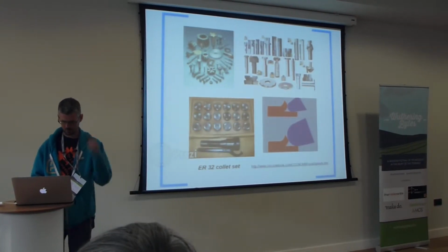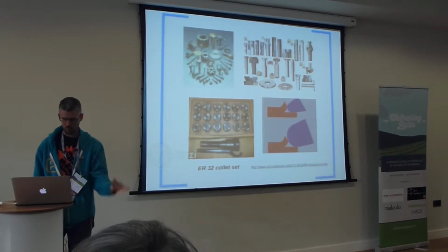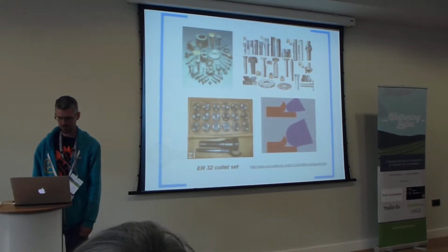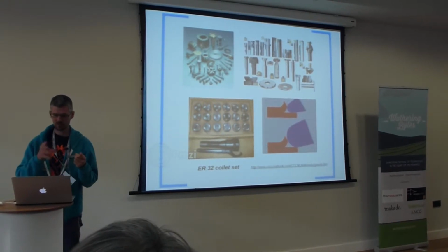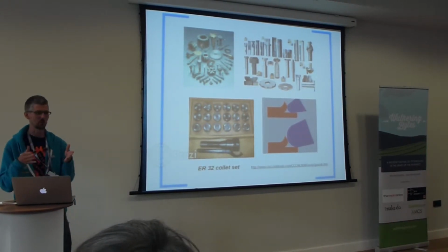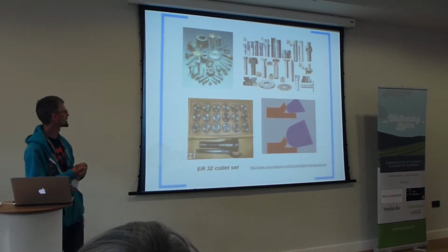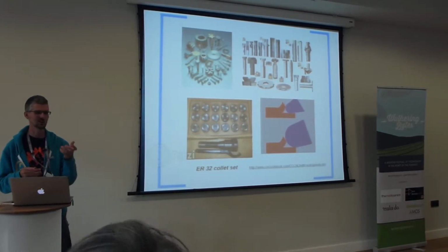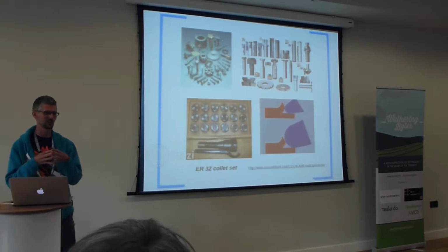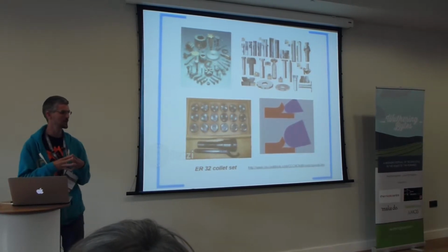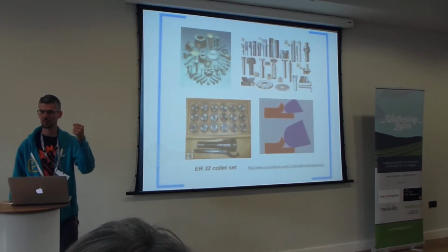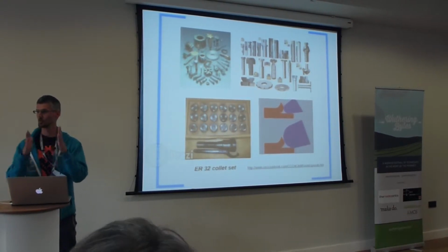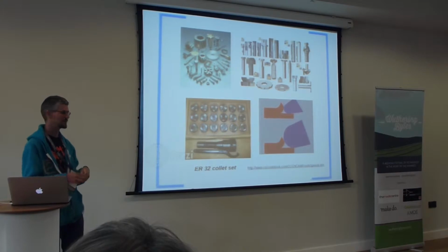So on to tooling. If you're used to things like pillar drills or cordless drills or whatever, you're used to having a chuck that can take any size bit, but the way that milling works is you usually have a specified shank size and then you get a range of tools with that shank size. So if you're, say, doing PCB work, pretty much the standard is 1/8 of an inch, so you need something that's going to hold 1/8 of an inch, and it doesn't matter what size your drill bit is, it's always going to fit in 1/8 of an inch.